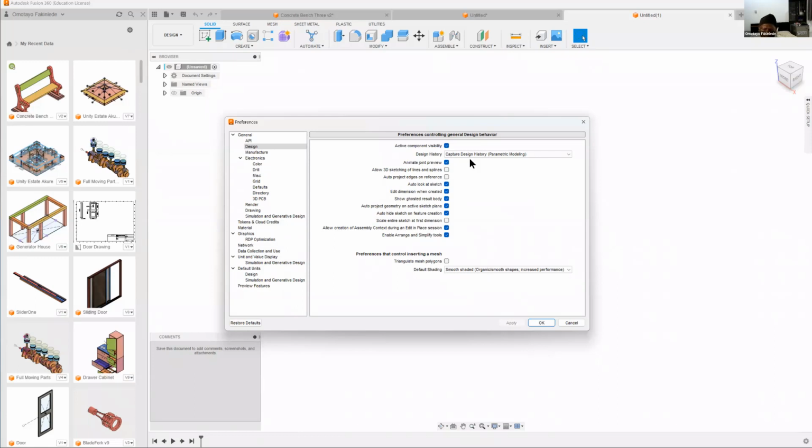So you see how design history works, because Fusion 360 is history-bound software. Everything you do, it records at what point it is done. So the hierarchy of how you did your work is saved for you. And it's also good for judging or marking your paper. If two people have the same design history, then that means they have copied each other, because even if you draw the same thing, you probably arrive at it differently, since there are many methods of getting there.